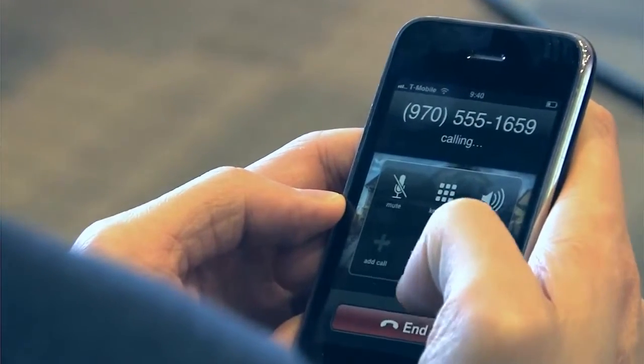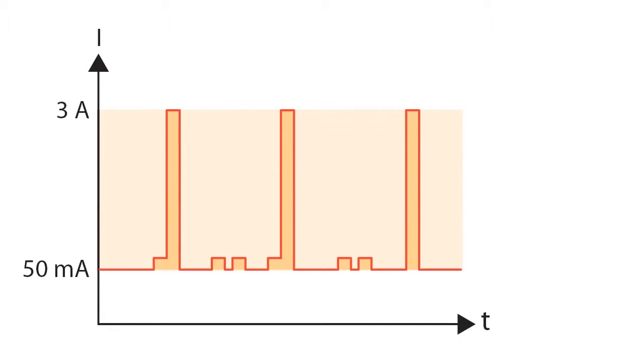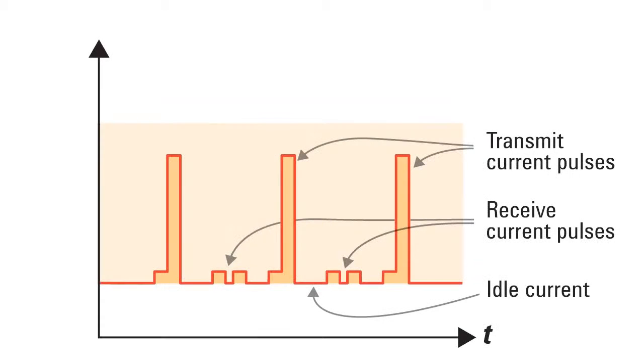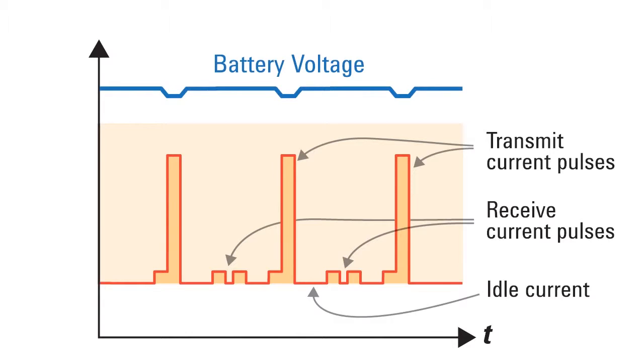The most accurate way to determine the expected runtime of a battery is to measure it under actual user conditions. High constant current discharge rates lead to reduced battery capacity. Likewise, high peak pulse discharge currents also yield lower capacity, compared to an equivalent constant current discharge having the same average value. The amount of peak pulse discharge that can be tolerated is highly dependent on the battery's internal design. Small differences in dynamic loading conditions for discharging can lead to significant differences in the runtime obtained from the battery.